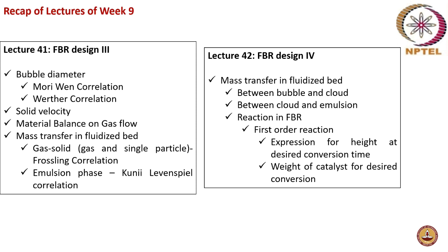And then lecture 42 was further continuation on the fluidized bed reactor design, and mass transfer in fluidized bed. The mass transfer coefficient between bubble and cloud, and then between cloud and emulsion was discussed. And then reaction in fluidized bed reactor, especially the first order reaction, was discussed, and an expression for height to achieve a particular desired conversion. And also, how do you estimate the weight of the catalyst for desired conversion were all discussed in the fluidized bed reactor design.